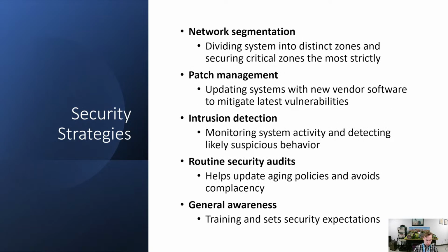Some other security strategies that you can implement to protect these systems, or just systems in general, are network segmentation. So dividing a system into distinct zones and securing the most critical ones most strictly. So you may have worked with systems that are very secure, but also very frustrating to work with because they are so locked down. So you want to be able to identify the systems that are most critical and make those have the most strict security measures. That's not to say other parts of the system shouldn't be secured or have strict security measures, but you want to at least create some type of prioritization because of how complex ICS and SCADA systems can be.